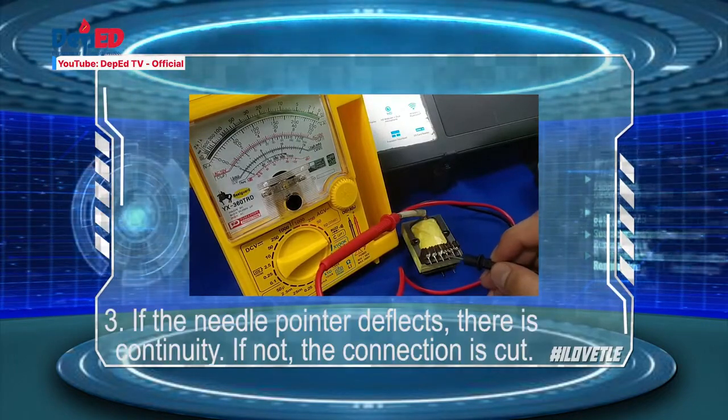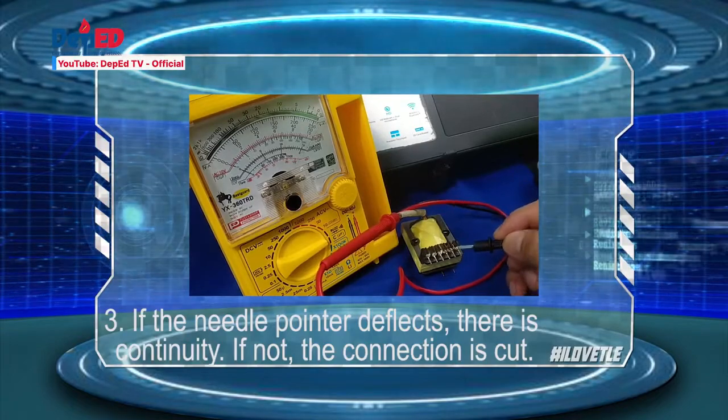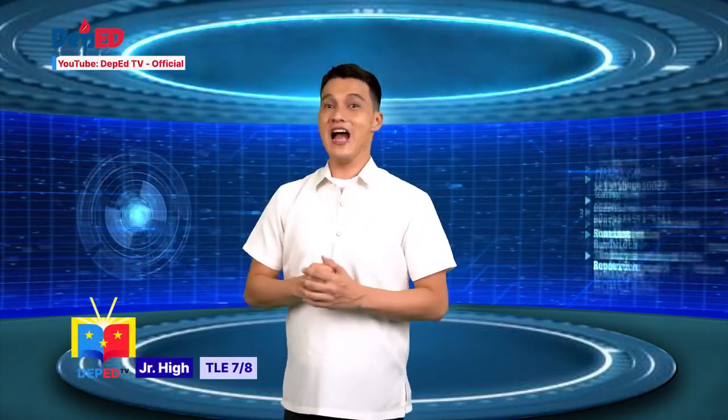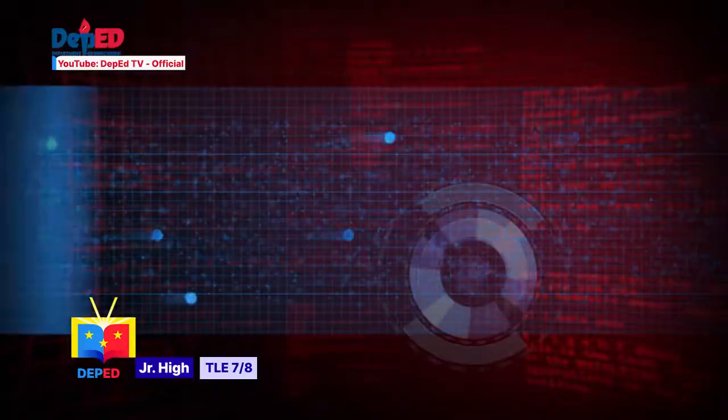If the needle pointer deflects, there is continuity. If not, the connection is cut. There you have it! You have just learned how to check a transformer by checking its continuity.